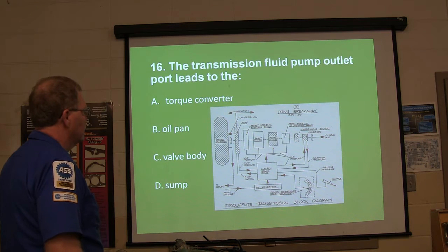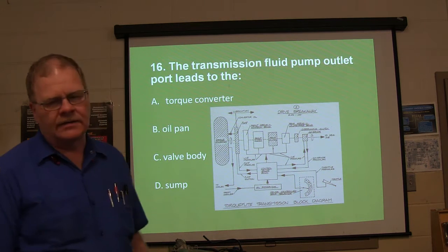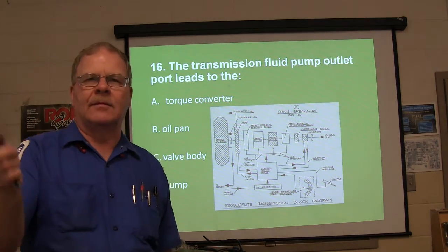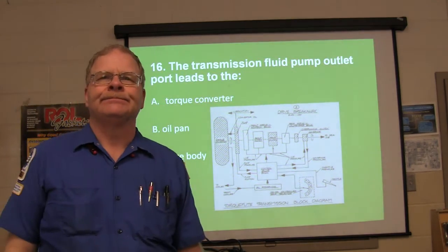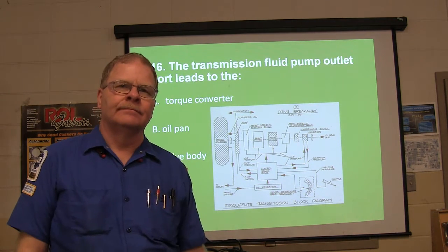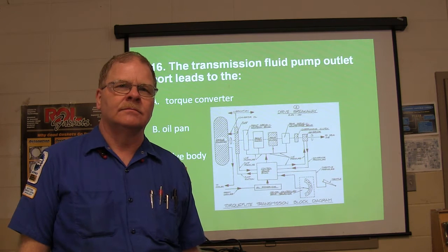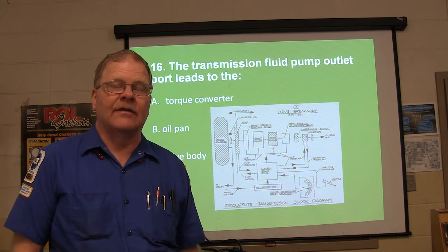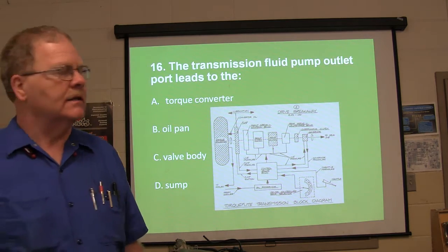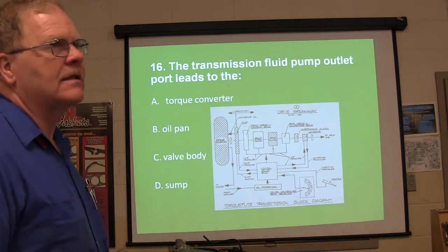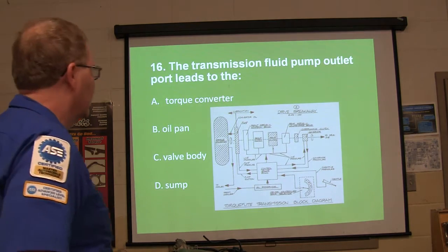When fluid's going back into the pan, it's by gravity, right? Well, it's actually coming back from the cooler. Yeah, but it's gravity fed. No, it's actually under pressure. It's coming back under pressure. I'm thinking about the oil pan then. Yeah, the engine oil pan, but not the transmission oil pan. It's two different things there. All right. I mean, there'll be a little bit of gravity letting it come back from some places, but the fluid that comes back into the pan.